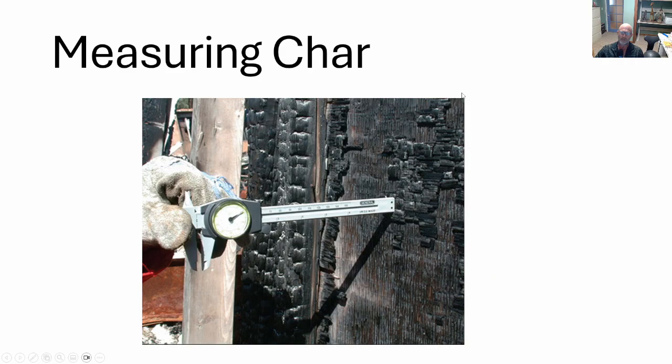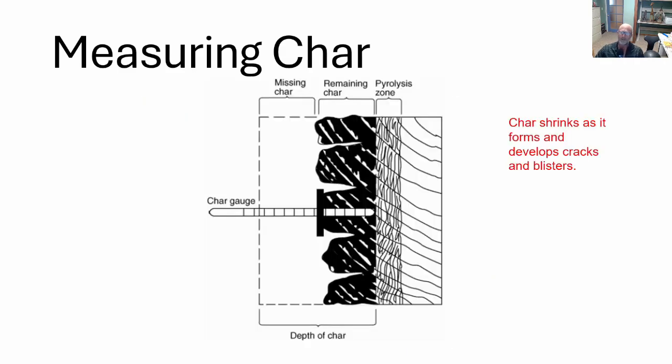And here's an example of demonstrating just that from NFPA 921. Char depth is actually measured not from the cracks that develop. Char shrinks as it forms and it develops cracks and blisters. Look for the solid char in performing this depth analysis.